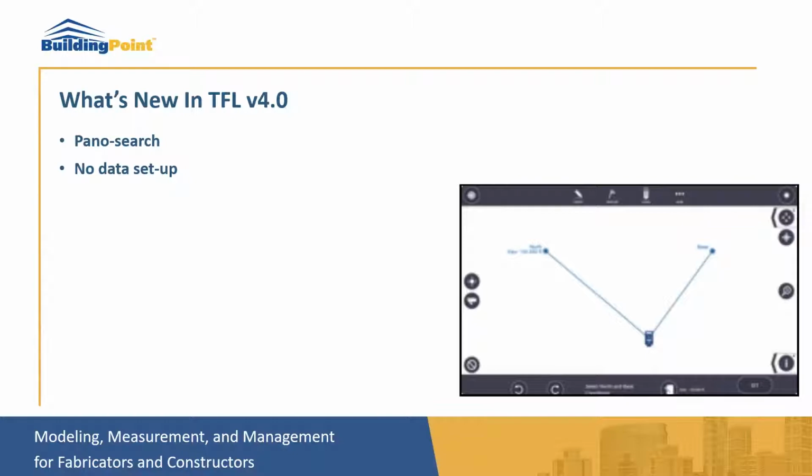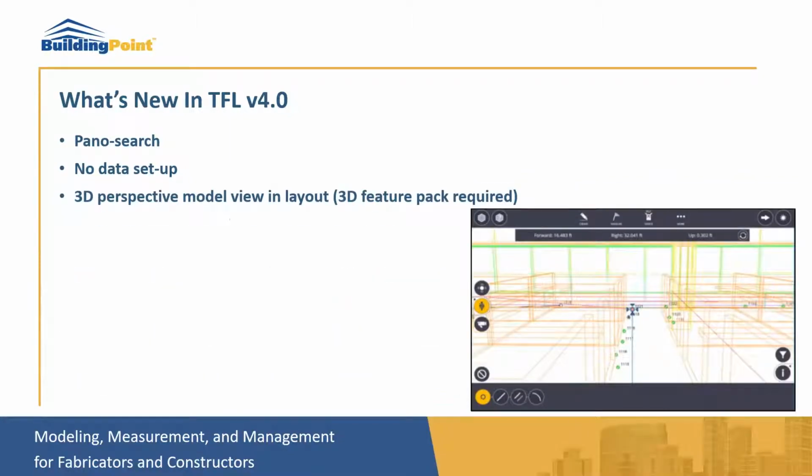So instead of struggling around with controls and establishing how we could set up our control points, you just affix 2 reflective foils on the existing barns, use that in a no data setup, and then you have at least your baseline with the 2 points that you just picked from your reflective foils. Then you can start keying in your plan and creating another barn that could be parallel at 50 feet away from that existing barn. Very nice, very useful feature for this type of application.